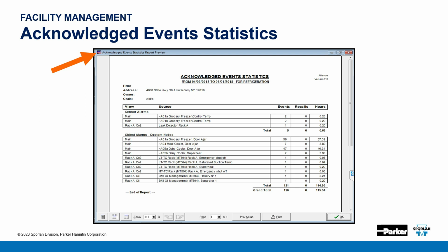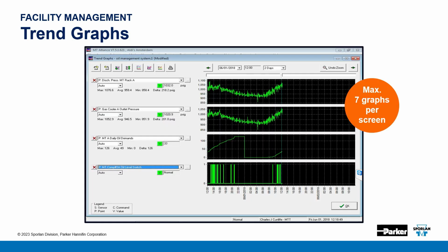With Microthermo, our philosophy is alarms do not disappear. They have to be acknowledged by a human. Either a store personnel or a technician has to react to the alarm. So what this does, rather than going through every single event that has occurred, it takes that and it aggregates it, puts it on report, and it helps you find the bad actors in your store or facility.